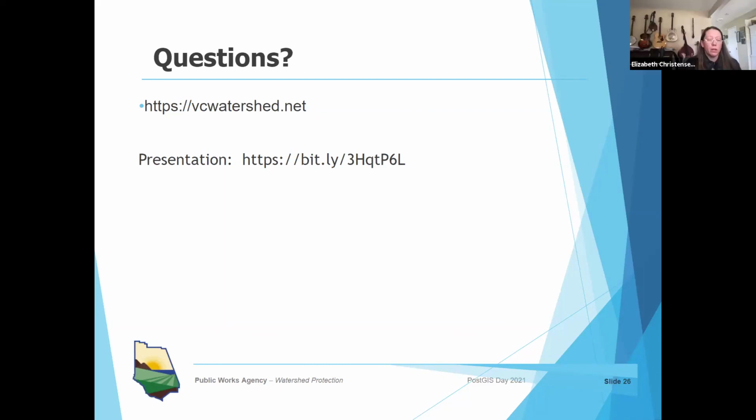Right. Exactly. And that's where it can be really nice, because you don't have one big inundation boundary for everywhere in the county. You have it at various locations. Maybe some sections don't need updates, but other ones do. Sure. You rerun the model, redo the boundaries, take the older ones out and put the new ones in, and you have an updated information library.